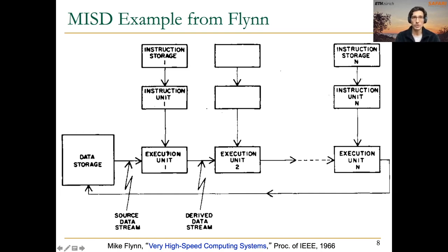Probably these execution units on a real system might be pipelined, which enables some parallelism internally, but conceptually, from the theoretical point of view, the execution units are operating on a single data element that follows the whole flow. This is similar to a systolic array, and we can consider it kind of a generalized systolic array.